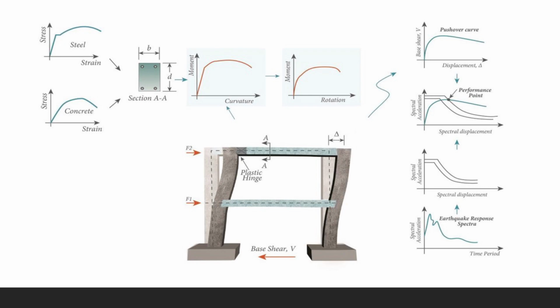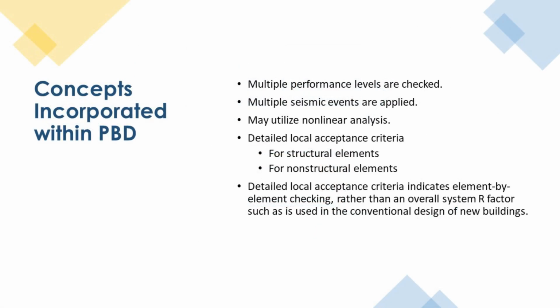It may require nonlinear dynamic analysis, and it definitely requires greater understanding of the actual structure that has been built. So that's the basic framework that we can use to do that. Once we have the framework, or we have the tools, the next important thing is that we define what are the hazard levels that we are going to check.